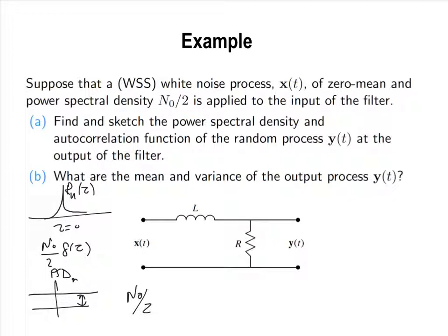And then we discussed a little bit, because noise spans all frequencies, then at the input of any communication system, you have to limit the bandwidth by using a bandpass filter, so that you limit the amount of noise coming into the system.